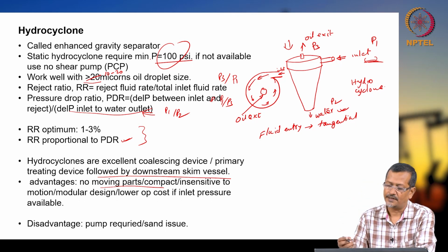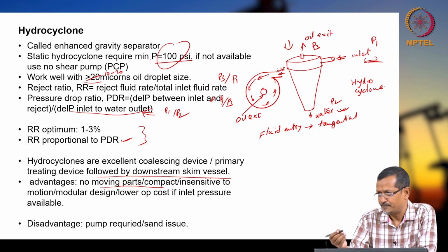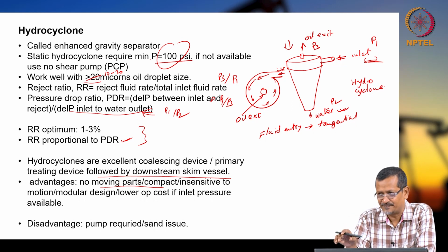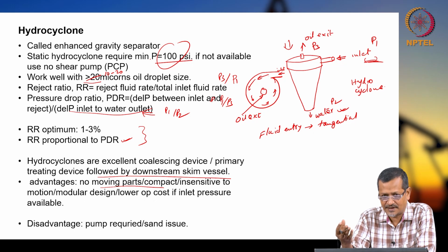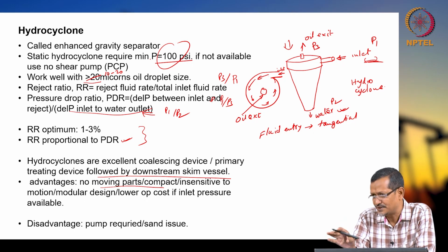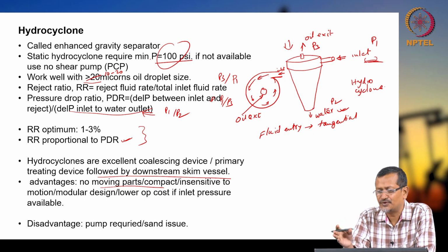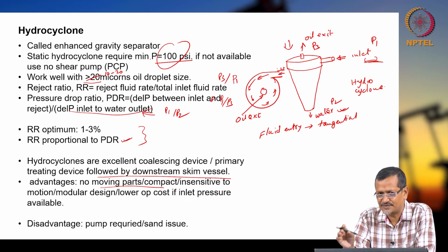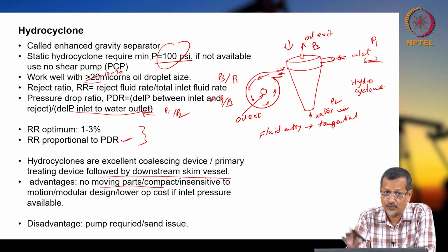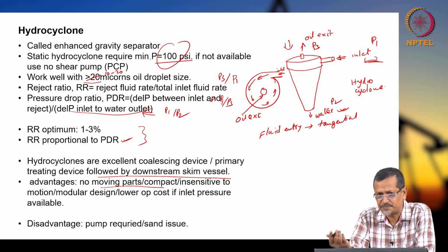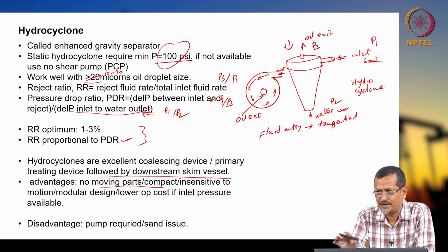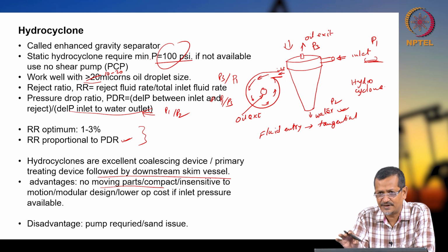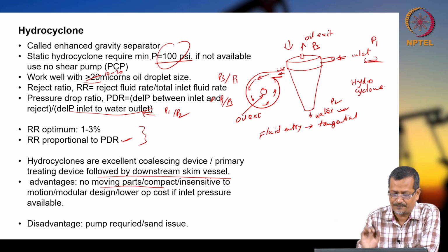But if you have any pump, then pump life will come into the picture. If you have more than 100 psi pressure, they will be cheaper actually, and you do not need any extra pumping mechanism. So, it is a very simple system. But if you have lower pressure, then you have to increase pressure with a pump. That will cost money, and it will reduce reliability also.